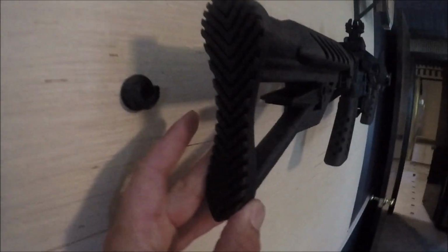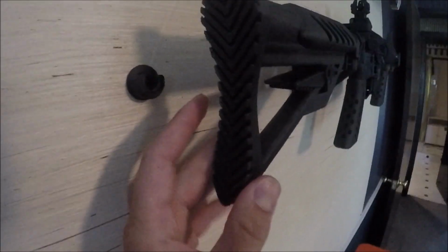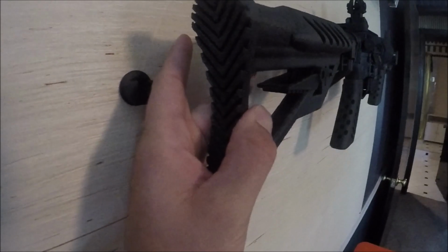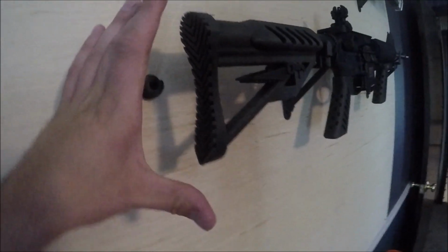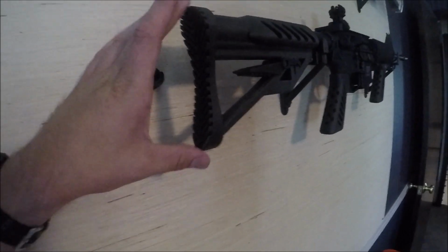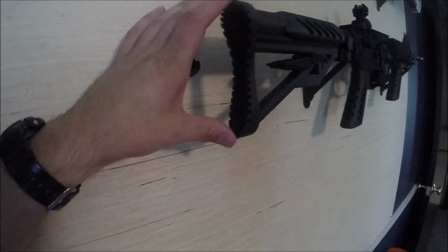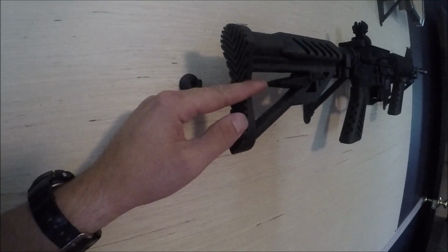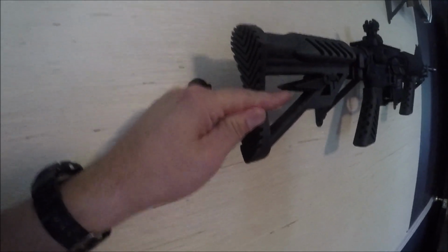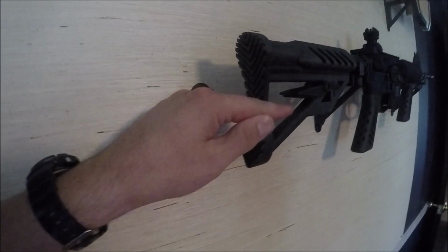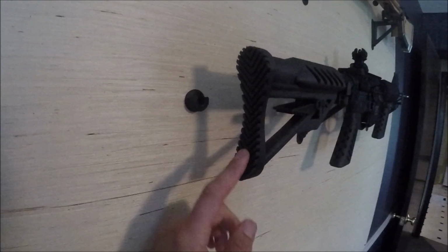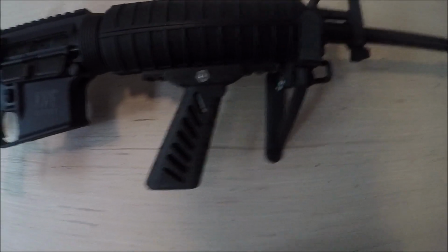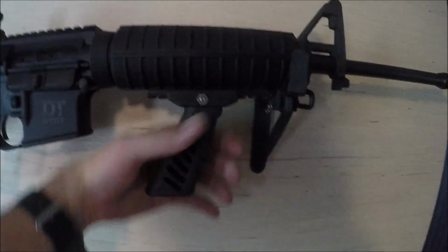We've also changed the shape of our butt pad. So this is designed to fit with body armor. It fits right in the section between your shoulder bone and your collarbone. There's enough mass, we extended this out a little bit, so there's actually more surface area for those forces to impact, which reduces felt recoil, but also this allows your shoulder to naturally hold on to the stock and the weapon, so you don't get as much roll to the right or it wanting to move up because of the aggressive texture we used.